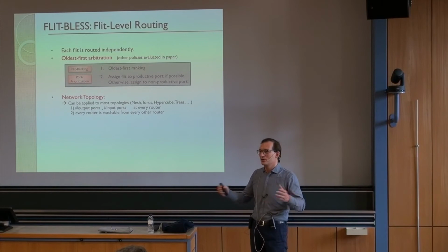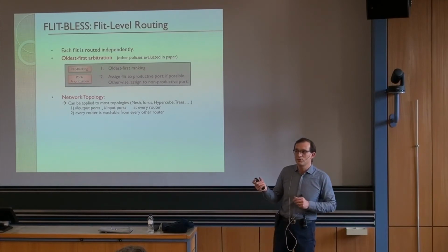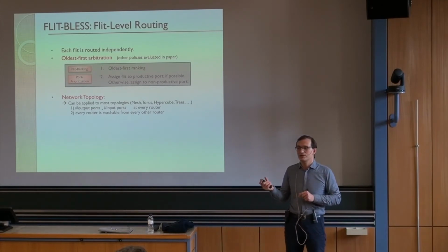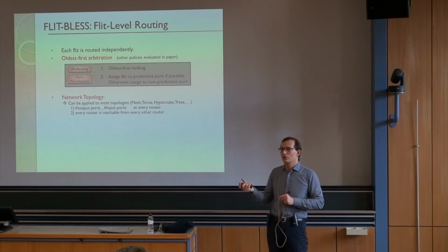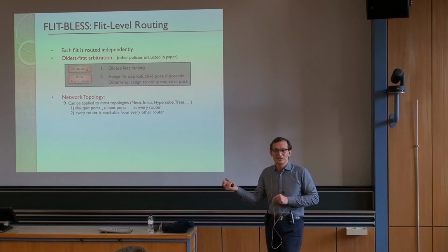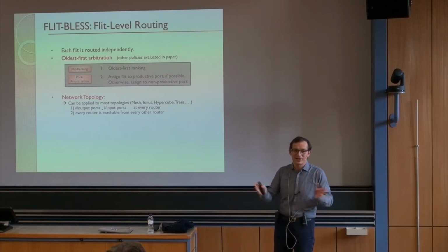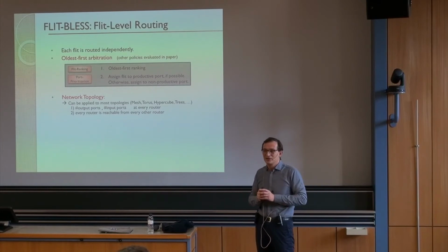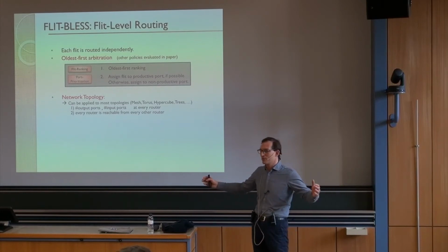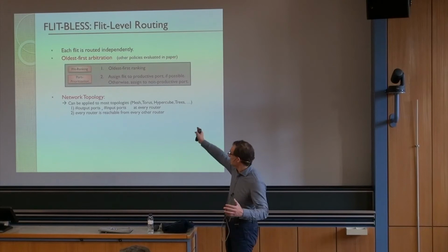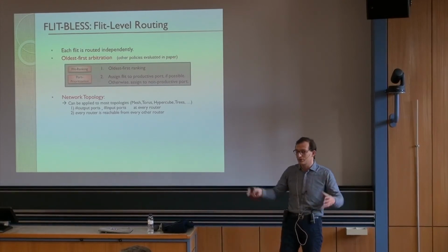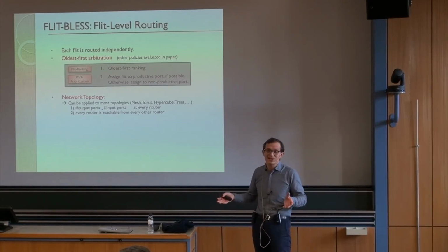If you want it for coherence reasons, most of your coherence packets are only a single flit, usually. They're control packets, and there is no breaking of the single flit in this case. So they arrive in whatever order they arrive. And most of your larger packets that are broken into flits that lead to this out-of-order delivery are data packets.